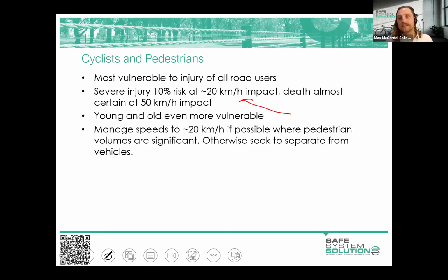The reason that we're bringing these key points into the discussion is if you were conducting a safe system assessment and it was outside a school, perhaps the way that you analyze the crash severity for particular crash types, you might bump it up a little bit in terms of the scoring because you're expecting lots of very vulnerable road users, lots of very young people in that area.